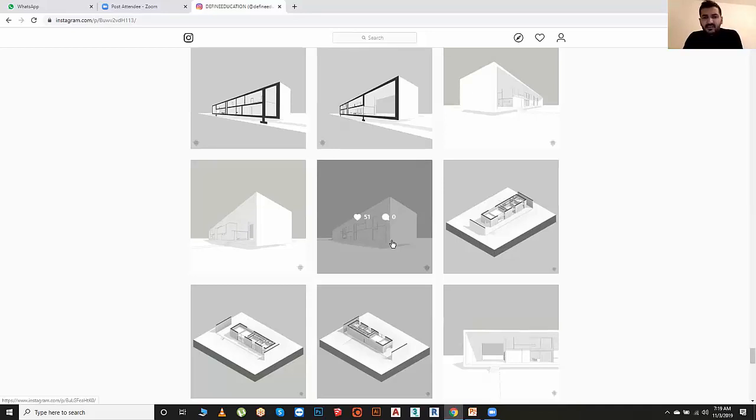And if not, you can try to find your warnings in Navisworks. For example, if you did one model and put it in Navisworks, it can find your warnings, for example, the architecture part with the structure part, the electrical phase or mechanical phase, and Navisworks can find all the warnings.